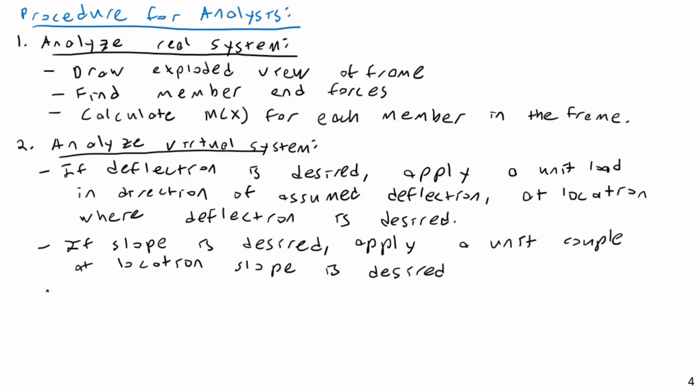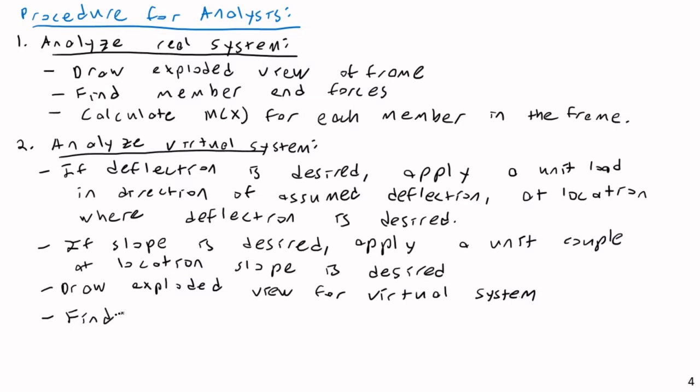And then you'll draw the exploded view for the virtual system, and then finally find mv as a function of x, the virtual moment as a function of x, for each member in the frame.